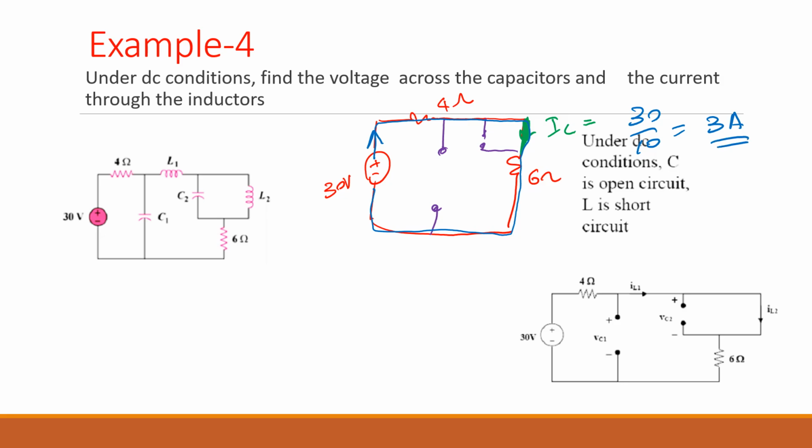Any question? So what is the voltage V1 and V2? V2 is the voltage in this path. So there is no resistance. Short circuit, always the voltage. If it is a short circuited path, the voltage across the short circuit will be 0 because the resistance is 0. V is equals to IR. Wherever you have resistance is 0, that means short circuited means resistance is 0. So your V2 is 0. Agree or not?